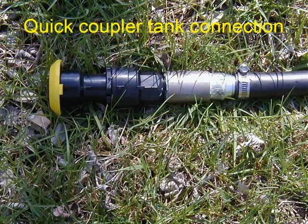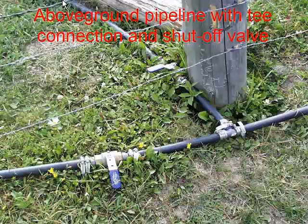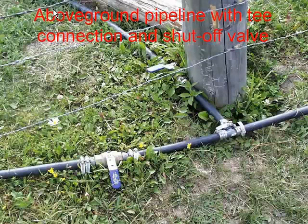What these allow you to do is move tanks around in the field. You can have valves to control where you're sending water to which tank, tees. These systems, if you notice, are pretty easy to put together. If you look, you've got some pipe bands there for attaching the HDPE to your different valves and your tees and whatnot. Very easy to use. These pipes typically go along, you'll notice in this picture, the fence line, which is a good place to put pipes that are above ground like this. It keeps them out of the way of the livestock and out of the way of equipment.